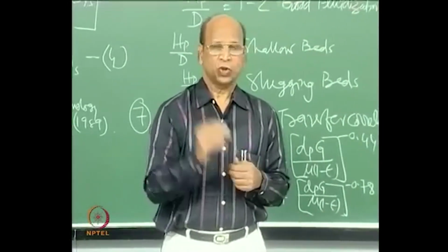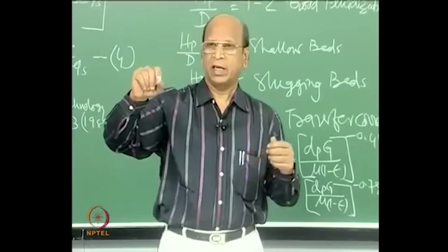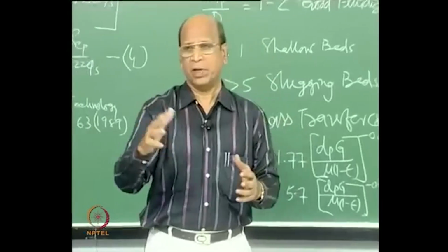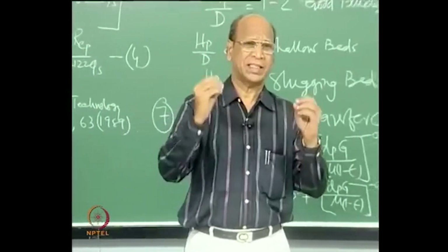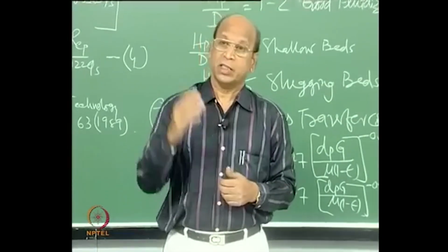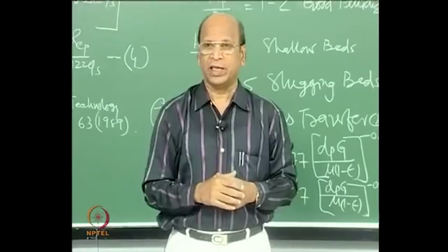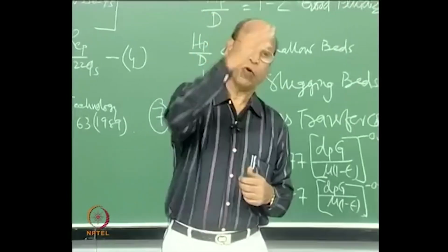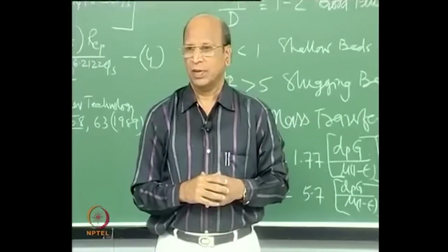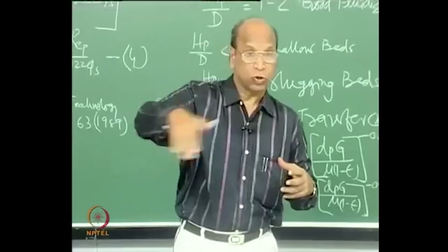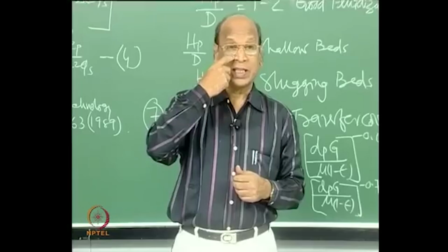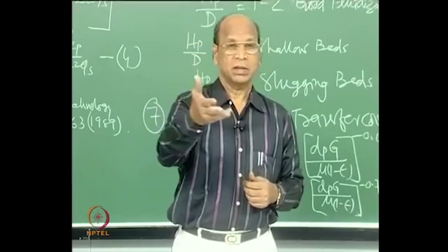When they plotted k tau versus x, the entire graph had points from different particles, for the same reaction, same catalyst, same conditions. Then they also drew theoretically the plug flow line and the mixed flow line, because we know only the first two ideal reactors. These are experimental points. They found that the conversion is even much less than in a mixed flow reactor.